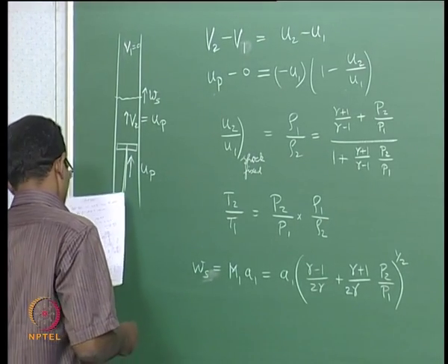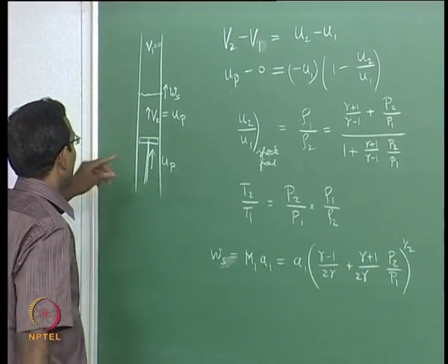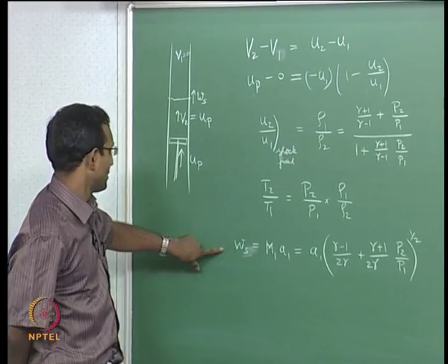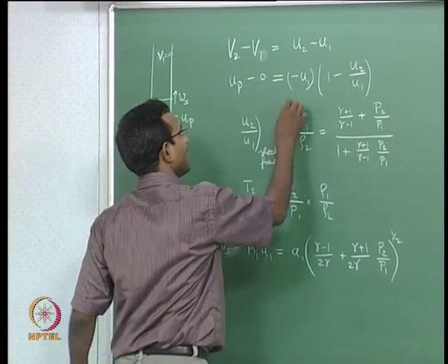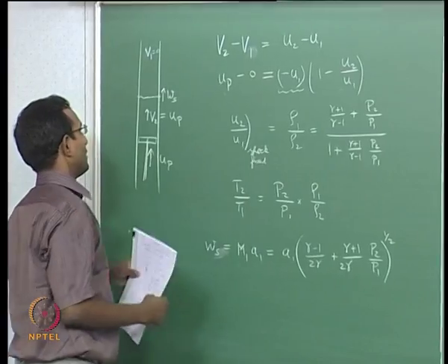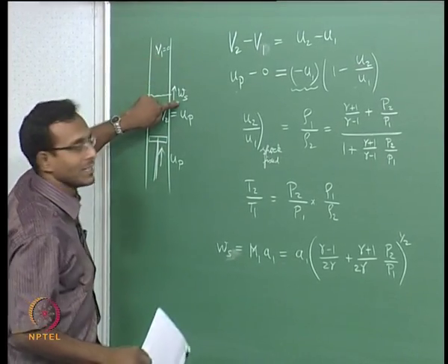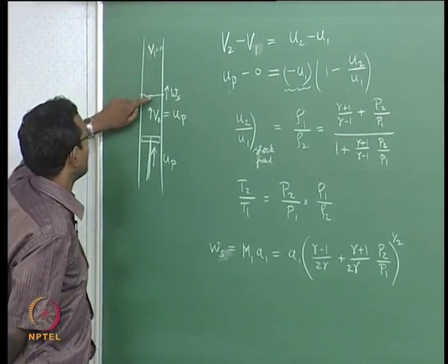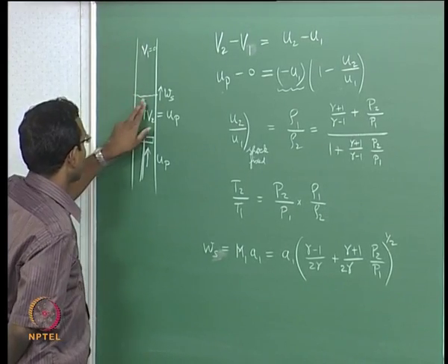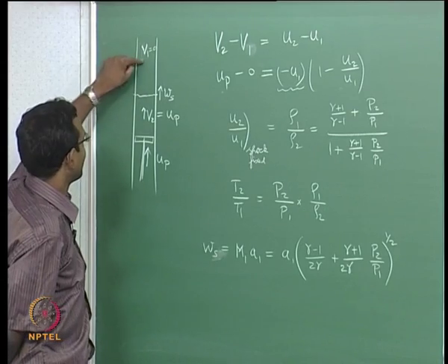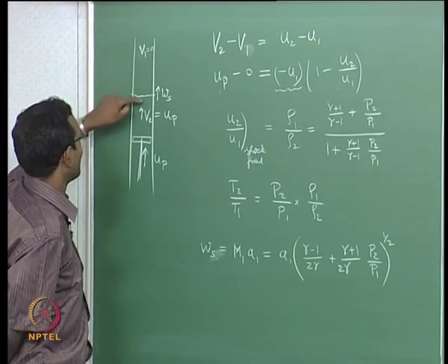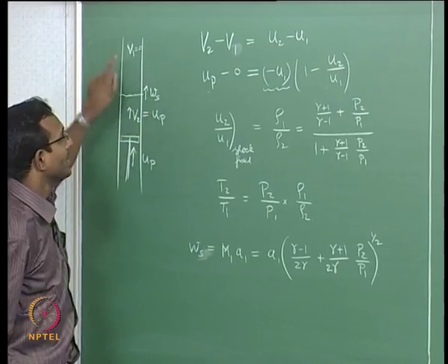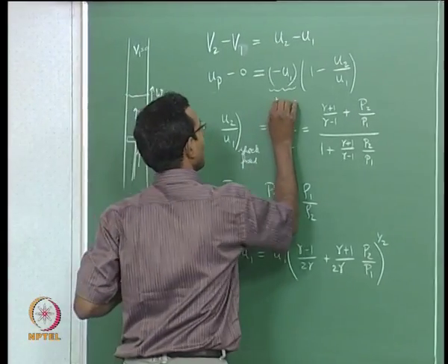Now, if I want to find the actual velocity behind this, I can find that by substituting inside here, where this minus u1 is nothing but the velocity Ws. Why? I am assuming v1 is 0, very important. Because of that, with respect to the shock, the incoming gas velocity will be equal to the shock velocity with respect to that gas. They are standing, my bus is moving. Equivalently, I see them coming in with the same speed as the bus, same relative example. So, minus u1 will be my Ws.